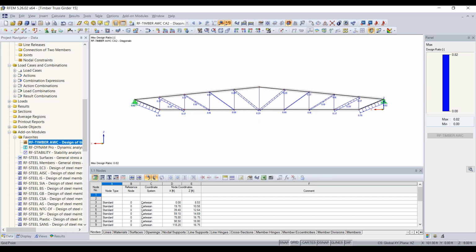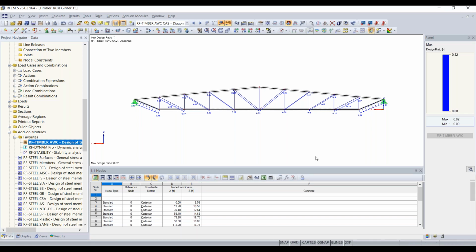The only question that came in was the ability to analyze shotcrete. I had answered in the chat, but just to clarify this, realistically, if there doesn't exist a material in the program, you can always add a user-defined material. As long as you have those properties, you can essentially copy the existing concrete material and add in the shotcrete material properties, then the full analysis can be completed.